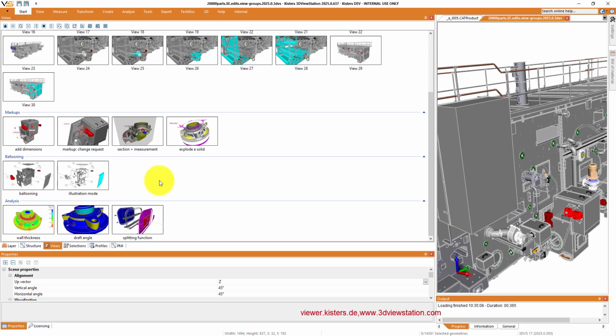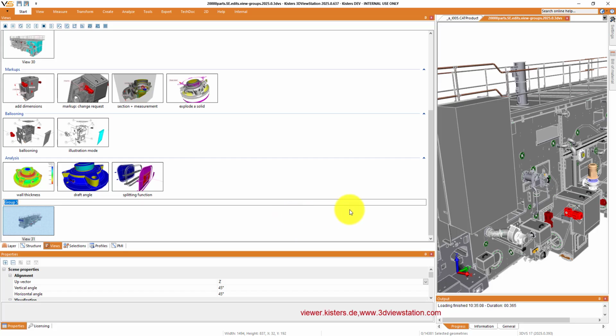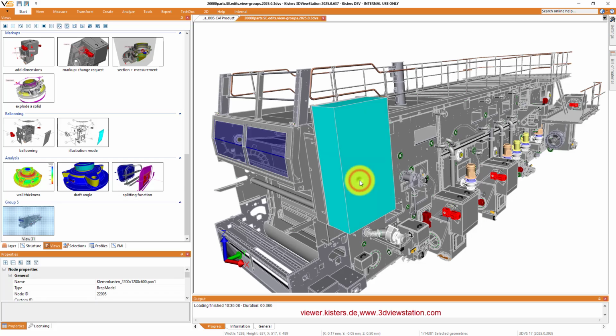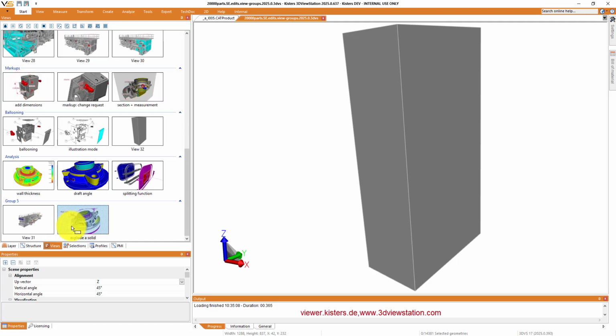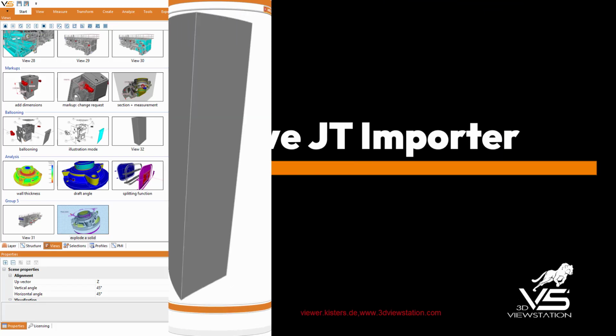Here you see a whole set of views for different topics. If you right-click on the views pane, you can create a new group, and this will automatically create a view inside. The new view is created in whatever group you're currently working in, so you can drag and drop it into another group.